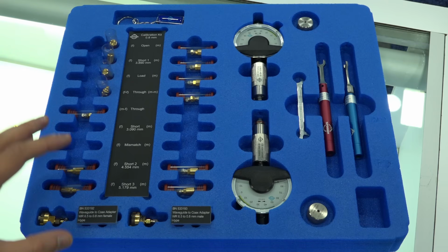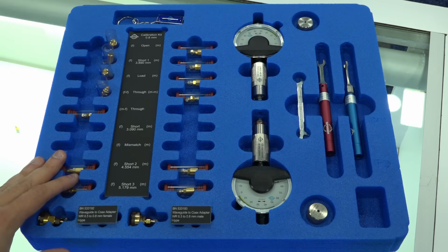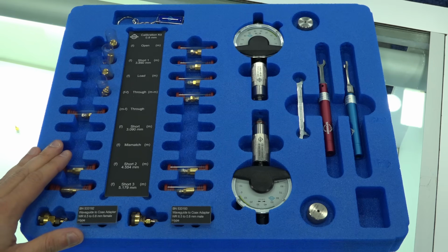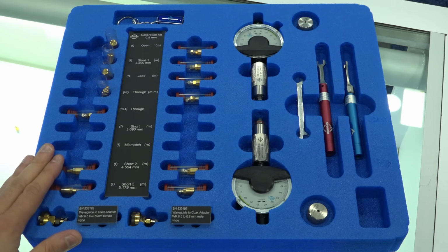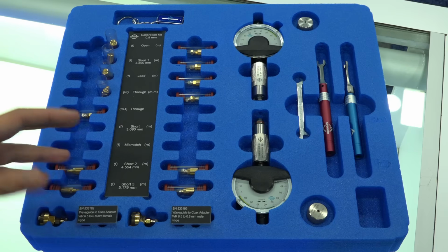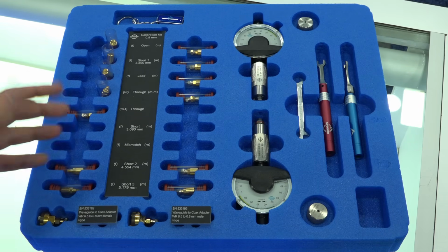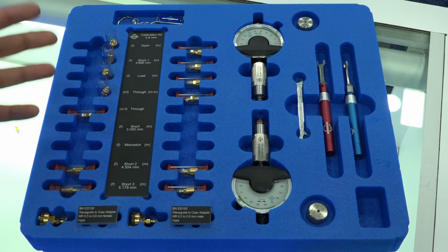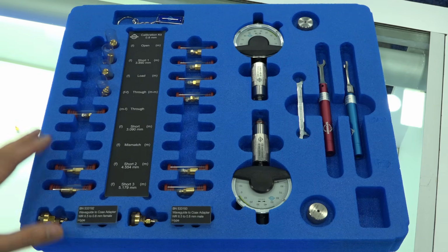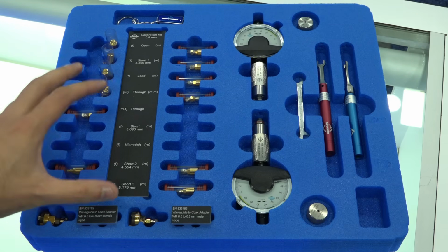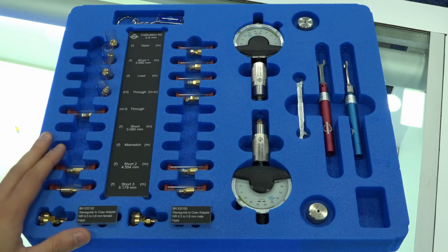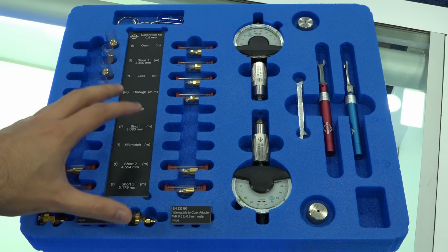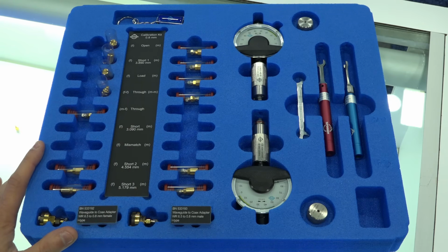So in the world of calibration, especially single sweep systems that go above 140 gigahertz, calibration is always going to be an issue. Now these single sweep systems are intended primarily for things like coherent optics, where you're trying to get above 200 gigabaud or so. So this, from Spinner, is the only 0.8 millimeter traceable calibration kit that exists today. And in fact, this one does go all the way up to 167 gigahertz.